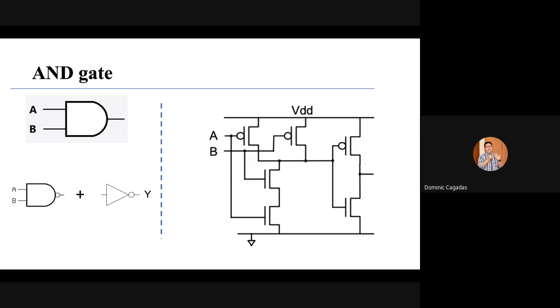So here is the question, sir. Are AND and OR the same? I was surprised, sir, because the circuits have different formations. Yes. If your input A is 0 and B is 1, then going to the PMOS, A becomes 1 and B becomes 0. So at least one is on, then the output also goes to 1, because your PMOS here is parallel.